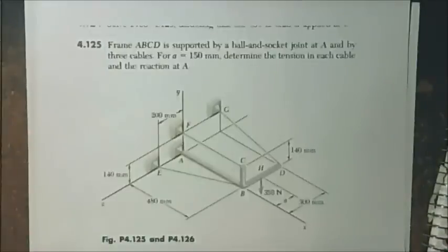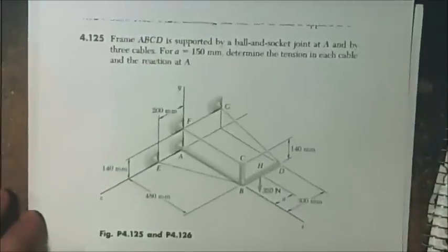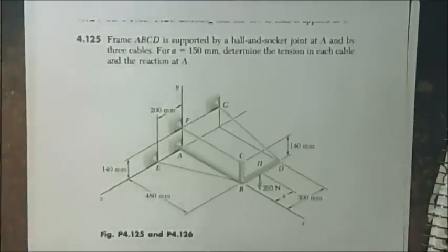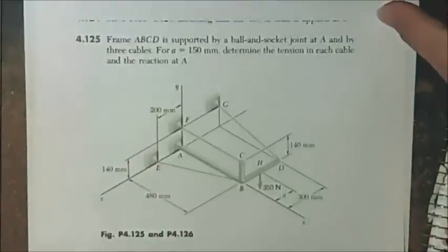However, in our class we were taught that you were only to use R cross F if you were dealing with a skewed line that is not parallel to any of the axis. For most of these problems, however, we are able to use the right hand rule and find the moment by using the force times the perpendicular distance, just like you would in a 2D problem. This method gets you the same answer, but it will be much faster, especially because most of the time you're going to be taking this as a timed exam, especially in the FE exam.